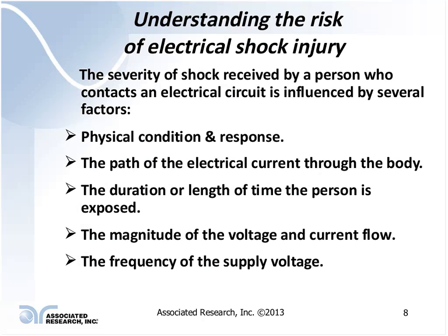So one of the things that we're trying to get across here today is that you do understand the risk of electrical shock and injury. Essentially, the severity of a shock that a person could receive is really influenced by several factors. The first one is the physical condition and response of the individual. The worse condition the person is in, the more susceptible they're going to be to possibly their heart stopping as a result of an electrical shock.